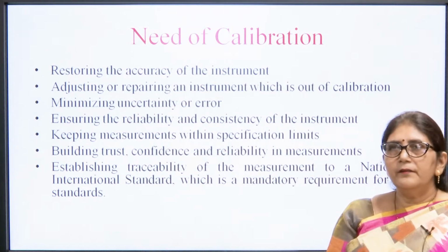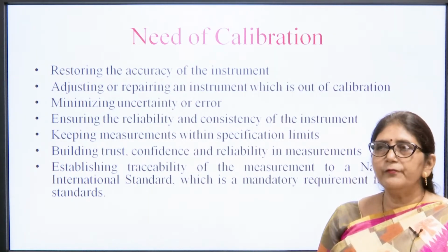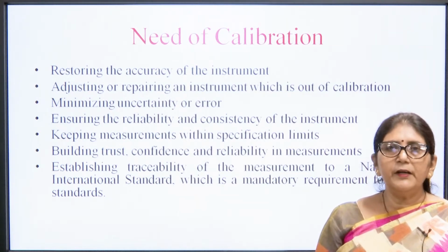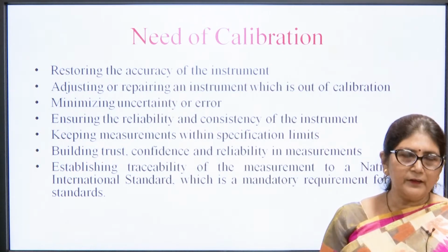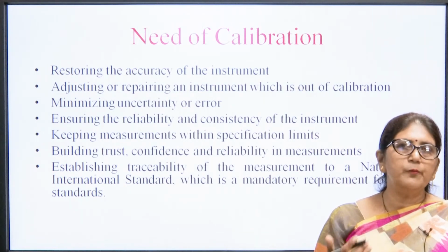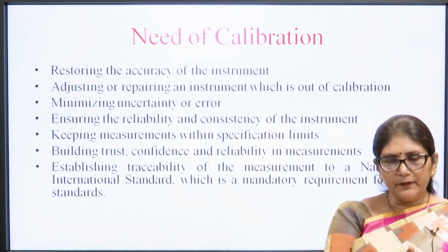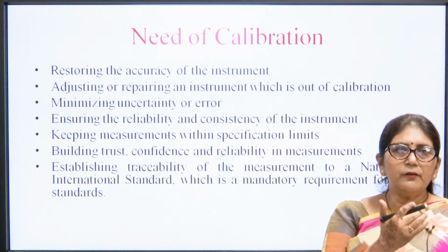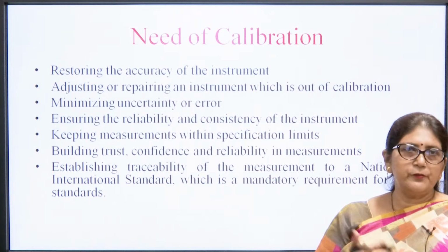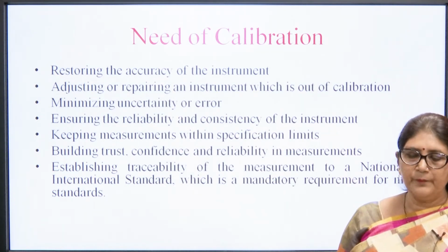So, generally in our college or for laboratory purposes, we can use a digital multimeter as a standard and we can calibrate the different analog voltmeters or analog multimeters by comparing the result with that digital multimeter. So, that digital multimeter also acts as a standard instrument for the calibration of the instruments that we are using in our college or our laboratory.